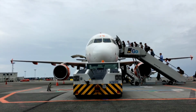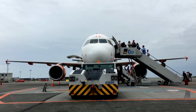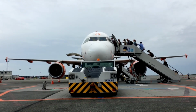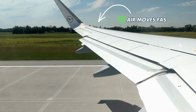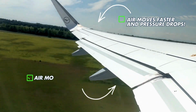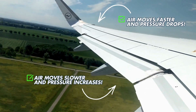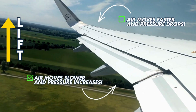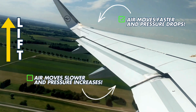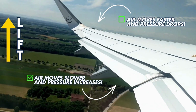To really understand winglets, we need to go deeper into how lift actually works. A wing isn't just pushing air down, it's creating a pressure system. Above the wing, air moves faster and pressure drops. Below the wing, air moves slower and pressure increases. This pressure difference creates lift, but nature doesn't like imbalance. Air always tries to equalize pressure, and at the wingtip, it finally has a chance to do exactly that.